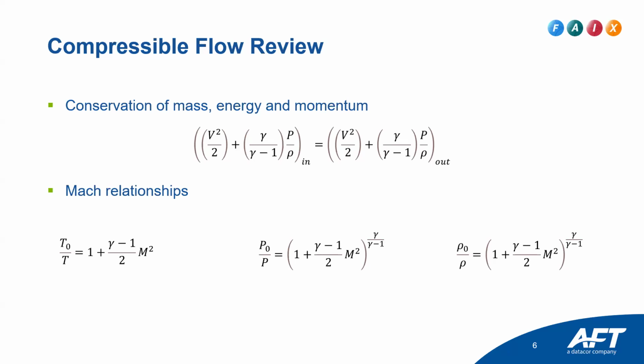What's the minimum pressure drop required through the air control valve to achieve good control? I believe you usually want them about 70% open. I'm not sure what the specific pressure drop would be. It would depend on the valve and the system. I should note that control valves, we can model them as failing. So if you wanted to see what happens when they fail to control and what state the system ends up as, you can model that.